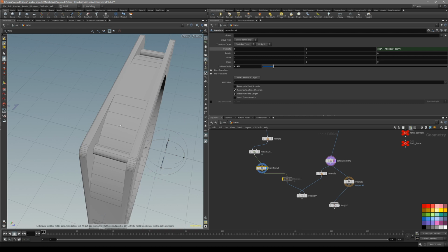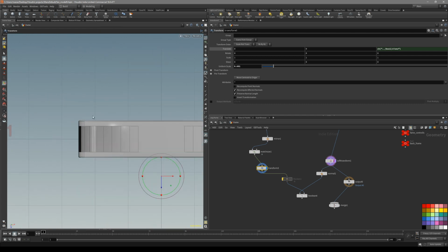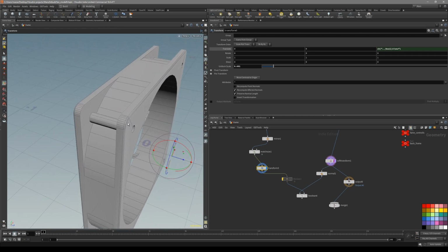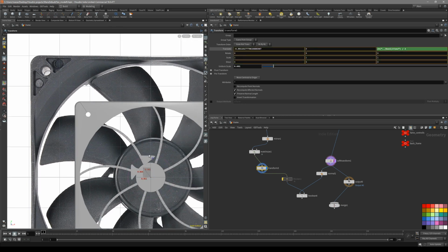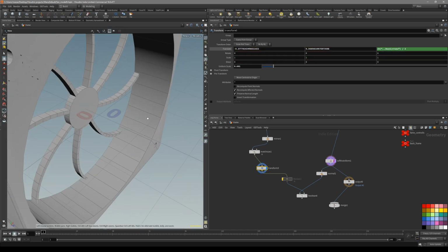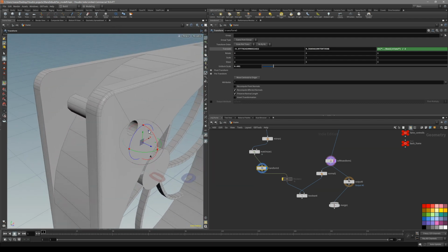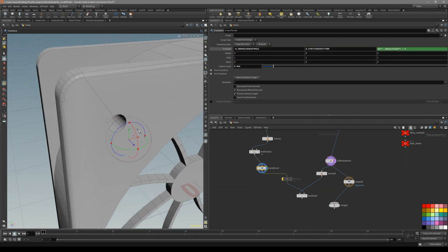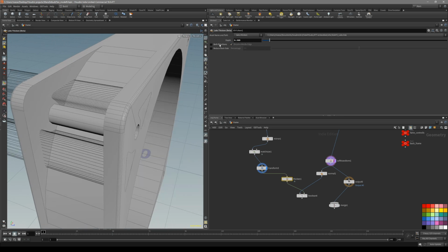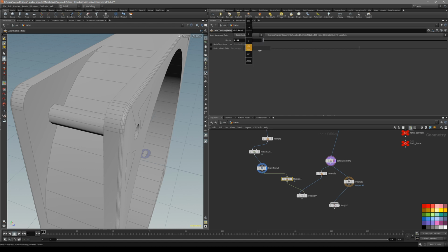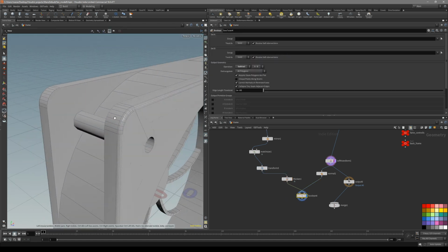But we know that our box is actually extending in the negative and positive. So all you have to do to match this side is divide it by 2, like that. If you take a look, now we move it around. It is right at the same surface as our box in here. You can see it, even the outline. And now with the thicken, you can also vote or not vote, whatever. You can see now, and now we can just make it a little bit and boolean out our shape.